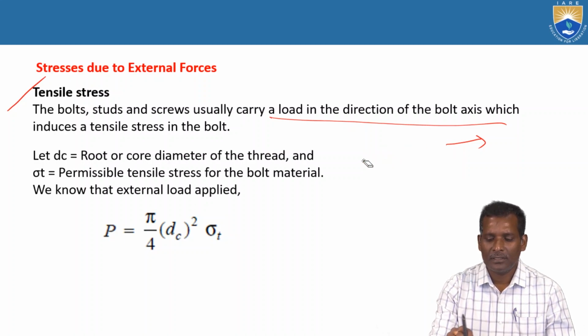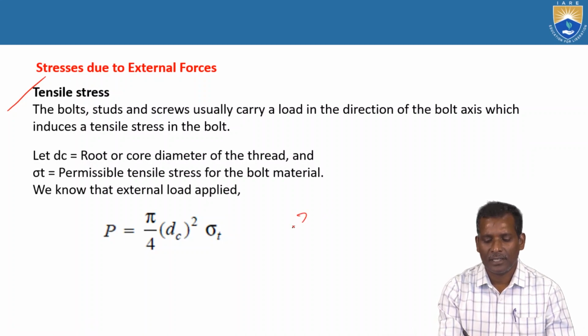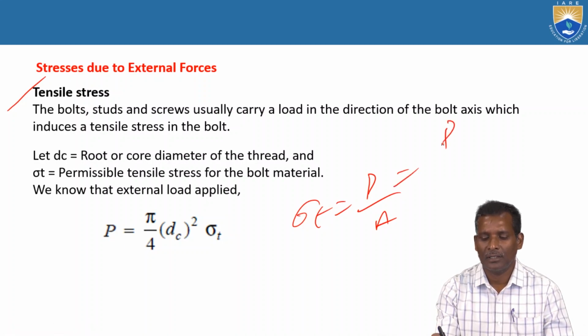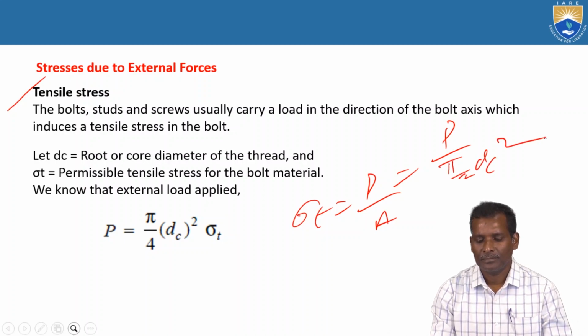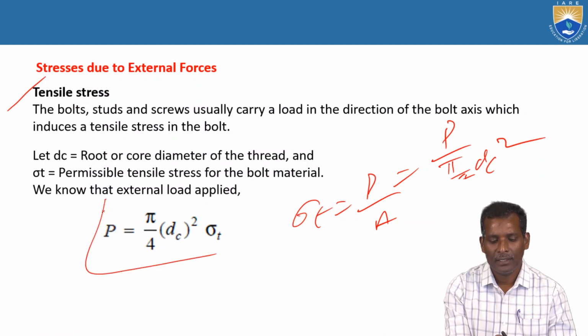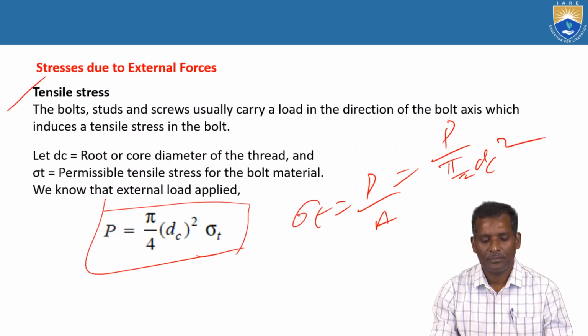In this case you can calculate the tensile stress, which is equal to load upon area. How do we calculate the area? Take the core diameter of the bolt, dc. So you can calculate the load by using this relation.